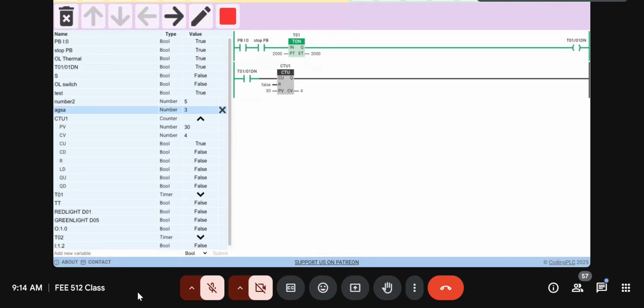The previous examples we did in class were modeled in this format, but now when you go to the simulator, you again have to modify the PLC ladder diagram. So with this, I realized that I can introduce the reset and preset model of the timer, so that we'll continuously get that pulsating signal to continuously set the timer for the counter to continuously count within the preset value of the counter. So I don't know what you have to say about that.